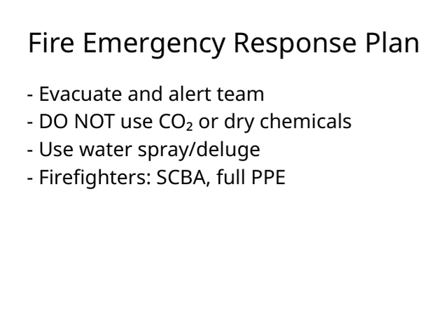Instead, the preferred method is to use water spray or a deluge system, which can effectively cool and suppress the fire. For firefighters responding to the scene, it's essential they wear SCBA, which stands for self-contained breathing apparatus, and full personal protective equipment. This gear helps ensure their safety while working in potentially hazardous, smoky, or toxic environments. Remember, having a clear, coordinated response plan is vital to minimizing damage and keeping everyone safe. This slide emphasizes the importance of choosing the right extinguishing method and proper gear, which are key components of our overall fire emergency response plan.